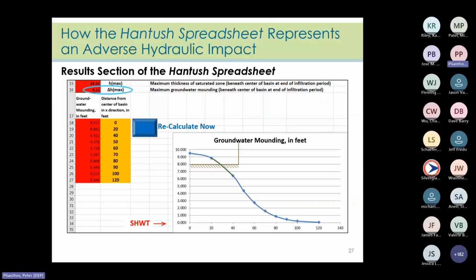So we have to adjust our parameters and run the spreadsheet calculation again. To do that, we have to reduce the value for R. We don't know exactly how much it will slow, but my first attempt would try reducing it by 50%. However, we are not ready to click Recalculate. The horizontal hydraulic conductivity is not adjusted since it is not affected by the reduced hydraulic gradient in the vertical direction. However, the duration of infiltration period must be proportionally adjusted to reflect the slowing down. For example, we would double the initial value for T if we halved R.